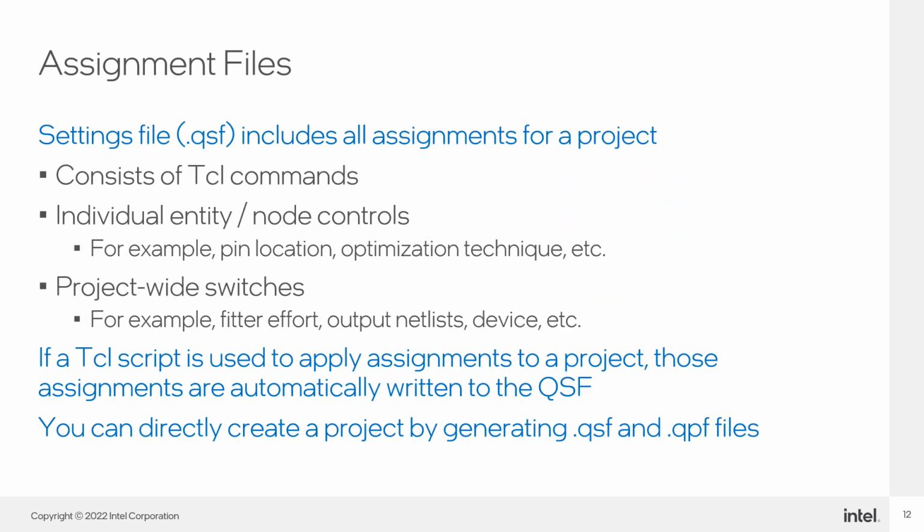The settings file, or QSF, contains all assignments for your project and is Tcl based. Assignments can be pin locations or optimization techniques applied to specific entities or nodes. They can also be project-wide switches, such as fitter effort, whether the fitter will generate output netlists, and so forth. One thing to note, timing constraints are located in the SDC file and not the QSF file.